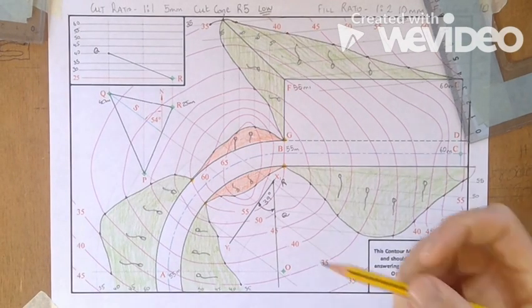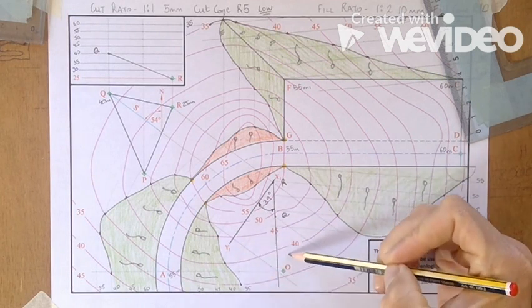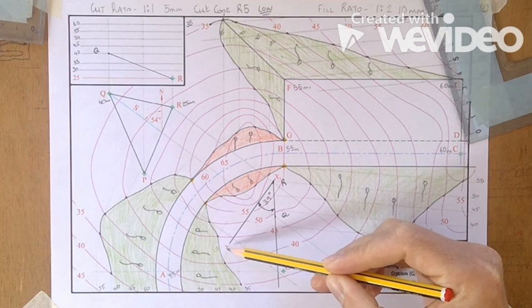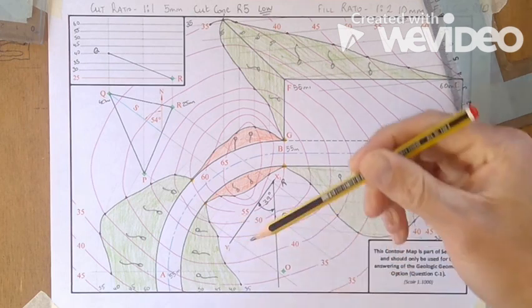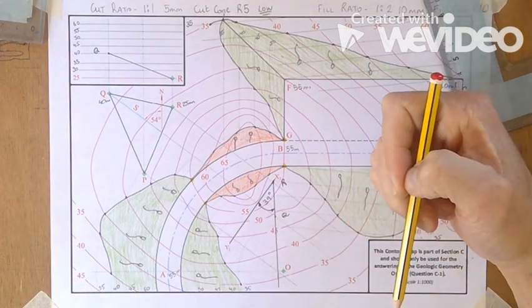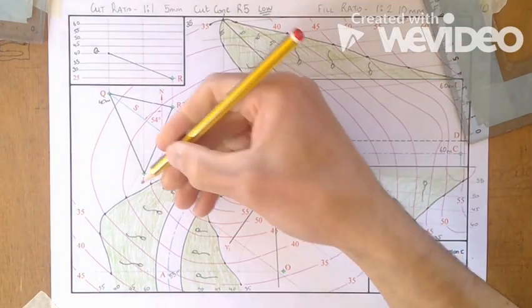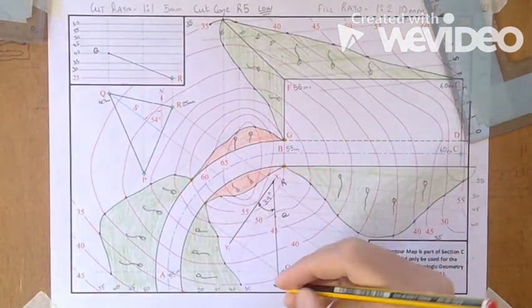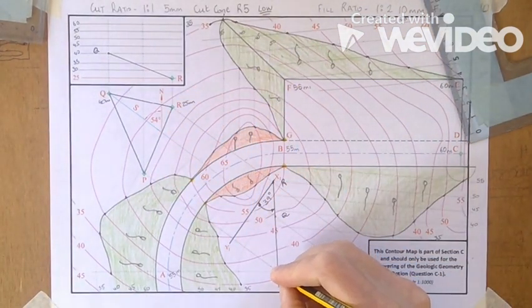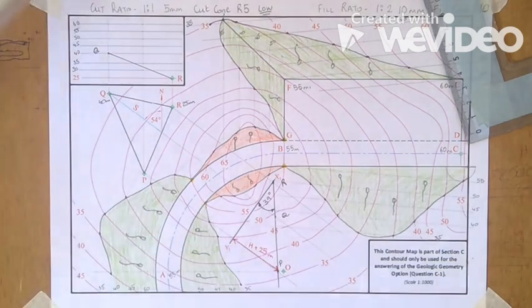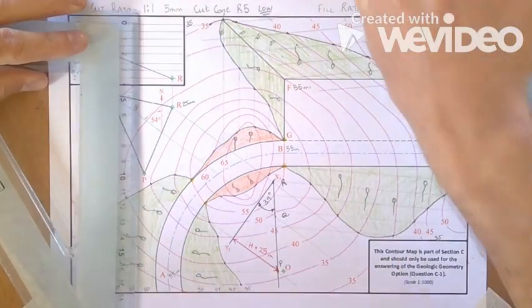Okay, so we had our auxiliary elevation view here. We said that the x1, y1 line was at a height of 25 meters. So if I measure that distance from there to there and add on 25, that'll give me the height of point P. Because when I bring out point P from my plan view, there's where the two of them cross there, so that must be point P. So when I measure that, I get 40. 40 plus 25 gives me a height of 65.